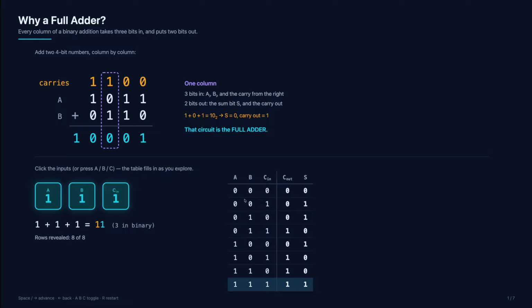And what I want you to notice is when you look at this, basically the output is the sum of the ones that you see between A, B, and C. On the first row, there's 0 ones, so this would be binary 0. On the second row, there's only 1 one, so this comes out binary 1. Skipping down here, you see 2 ones in this row, so that'd be 1, 0. And lastly, we have 3 ones, so that's 1, 1. So it's another way of looking at the output of a full adder. You just read it as counting.